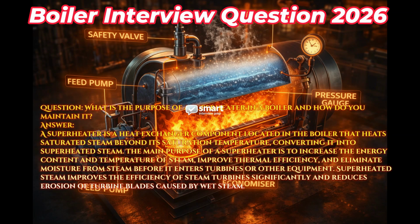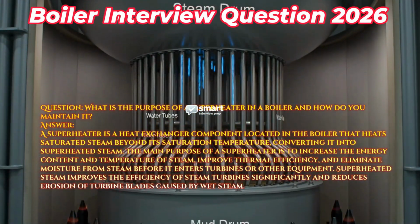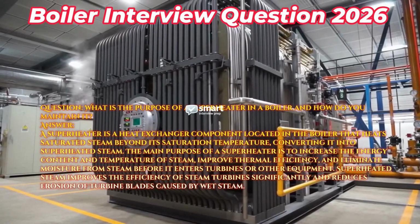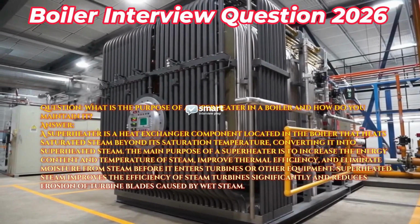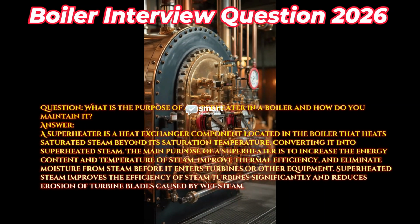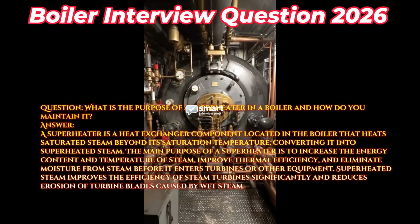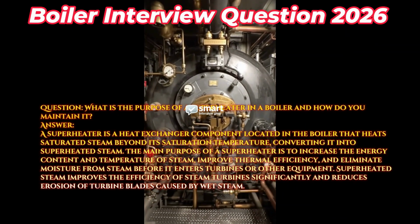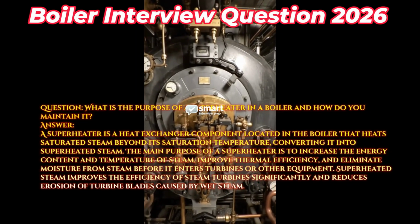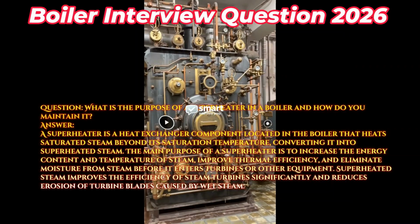Question: what is the purpose of a superheater in a boiler and how do you maintain it? Answer: a superheater is a heat exchanger component located in the boiler that heats saturated steam beyond its saturation temperature, converting it into superheated steam. The main purpose of a superheater is to increase the energy content and temperature of steam, improve thermal efficiency, and eliminate moisture from steam before it enters turbines or other equipment. Superheated steam improves the efficiency of steam turbines significantly and reduces erosion of turbine blades caused by wet steam.